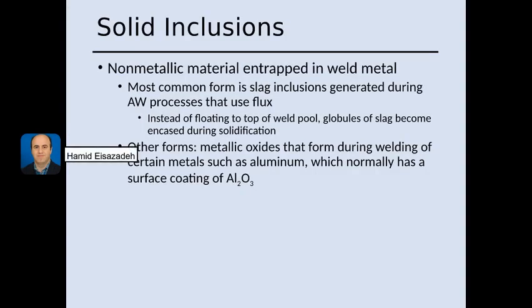The next defect is solid inclusion, where we have non-metallic material that is entrapped inside the weld metal. One of them is a slag inclusion. So slag is supposed to stay on top, but in some cases it may be entrapped inside the weld metal.